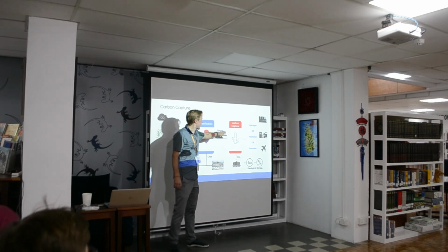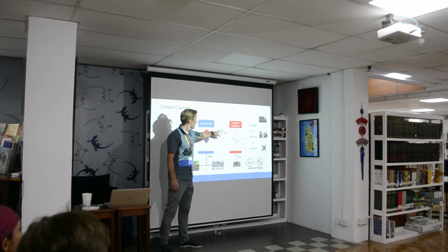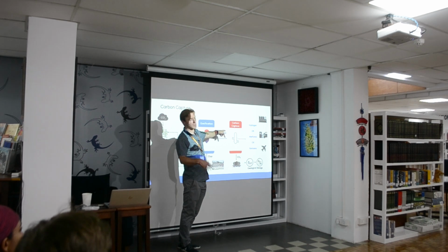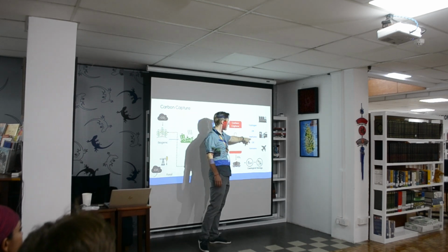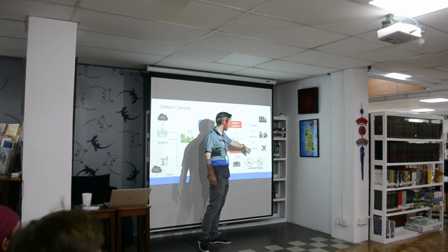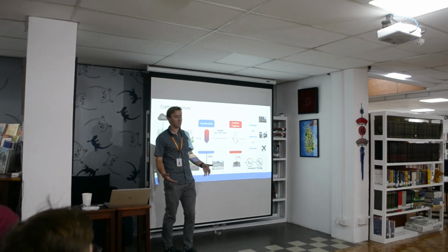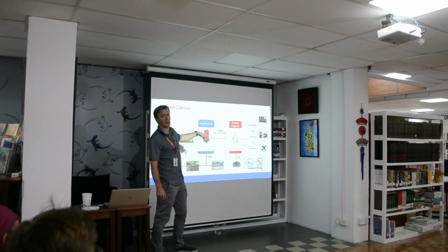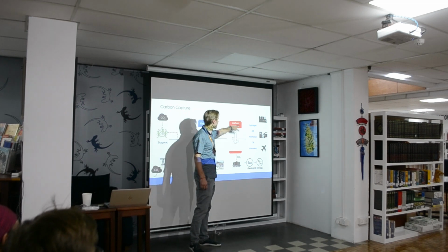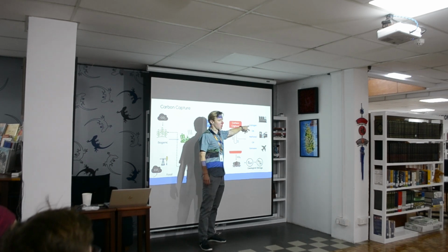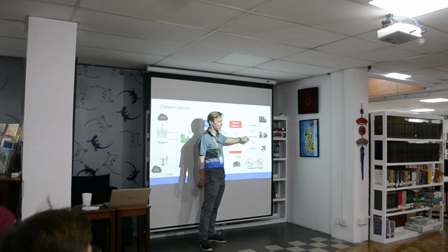So say you've got your syngas, this is your new product, you've got it from the waste, everyone's happy, you've got a valuable product. You can then process that further to go to different fuels, hydrogen, methanol, or kerosene, so that's like a jet fuel. Depending on the fuel, you would always have to have a carbon capture step in there to create that fuel. Hydrogen's the best option because there's no carbon left in there, whereas these do have a little bit of carbon.